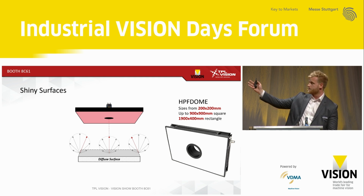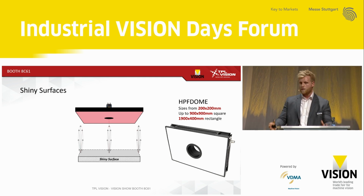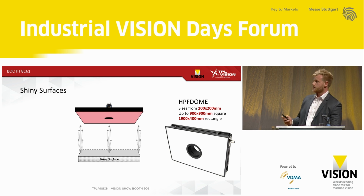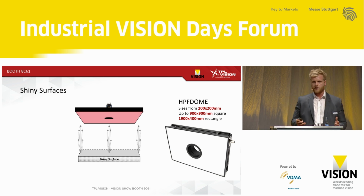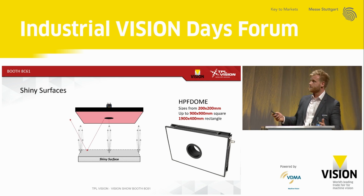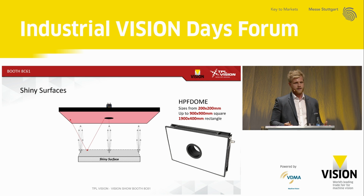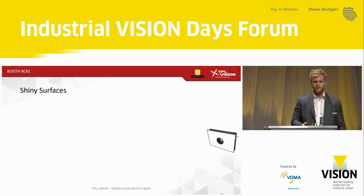However, if you look at something like this, this is a really diffuse surface. If you change that to a shiny surface, the way in which the light reflects is very different. You get a lot more intensity with the reflection, but it's a lot more directional. And in this case, when you're inspecting something shiny, you actually want to look at the light in the mirror. So you look at the reflected field of view, like that. And this is why there's general guidance that you always use a light that's double the size of the field of view. It's due to the way that you look at the light and imagine that it's a mirror.